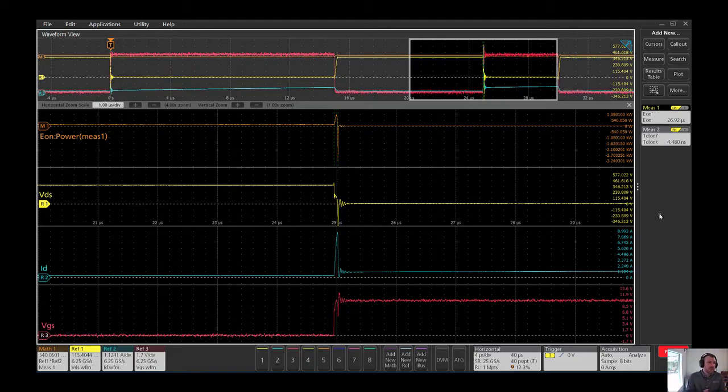Next, with silicon carbide and gallium nitride, our probe recommendation is the IsoView probe. It's optically isolated first off, which enables an incredibly high common mode rejection ratio. This helps you look at ringing, and you can really trust that what you're measuring isn't a function of a differential probe, right?